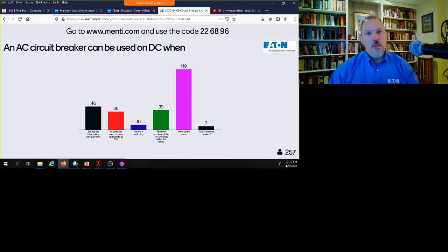The only way you can use a breaker that's listed for AC is when it's also listed for DC. Okay, you have to have circuit breakers that are listed for the application, and we'll talk a little bit more about that on how we get that done. But remember, AC current is a lot different than DC. What's the big thing that's missing? 0 crossings. Circuit breakers and fuses love 0 crossings. They eat them up. That's when we do our best in stopping that flow of current.